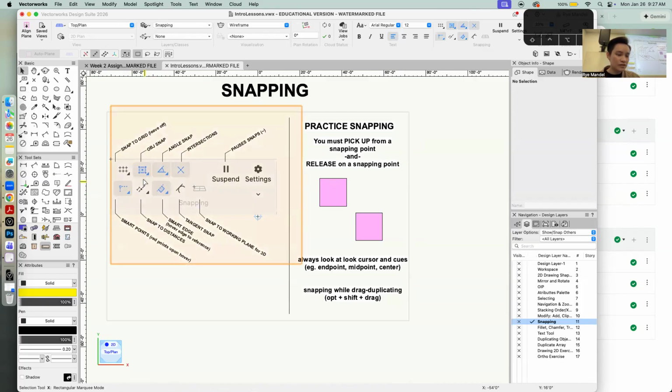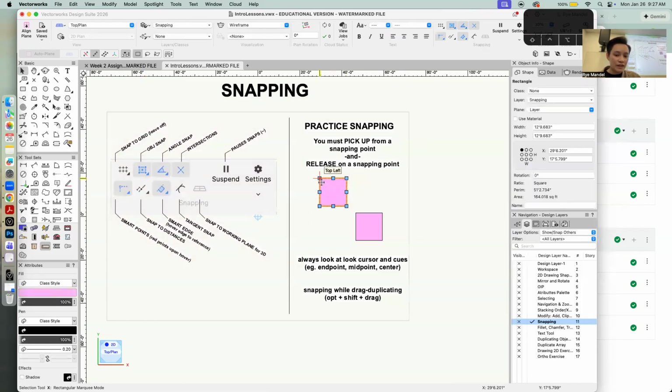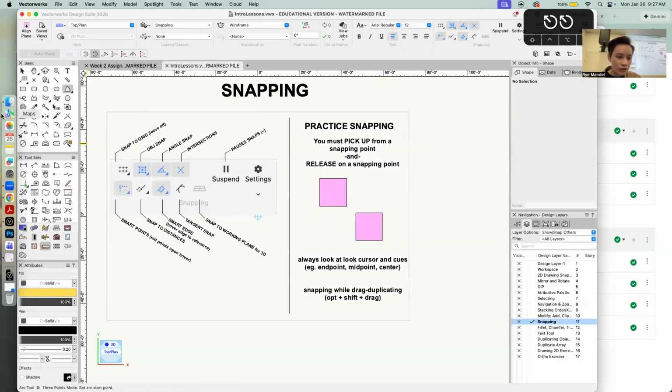So it would be object snap. So that would be snapping it to have these 4 points, or just the blue dots in general to have your vertices on. I recommend having angle snap on. Angle snap is really gonna help. If you have an angle, you can snap an angle to, let's say you have this and selective under this mode selected. It's the first mode underneath your arc tool. If you keep going and then hold shift, sometimes it will select certain angles for you.